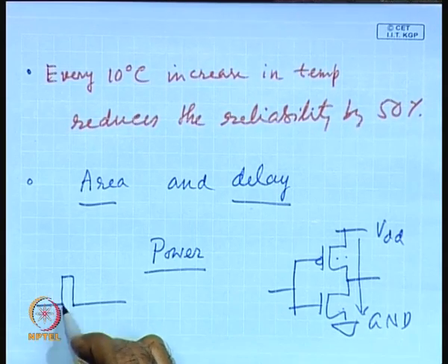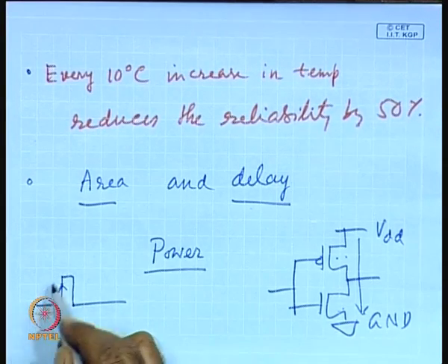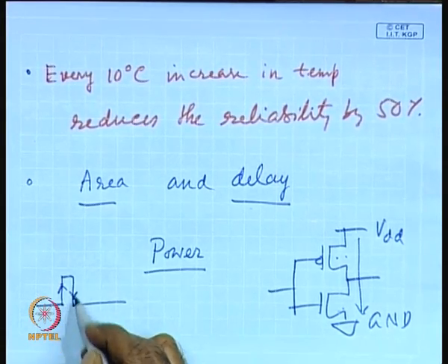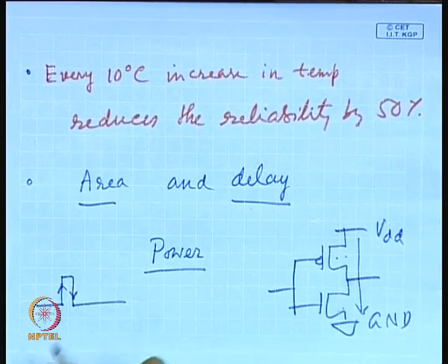That means again for charging, whenever it goes from 0 to VDD, and also power dissipation occurs when the glitch signal goes from VDD to ground. So, this is glitching power dissipation.